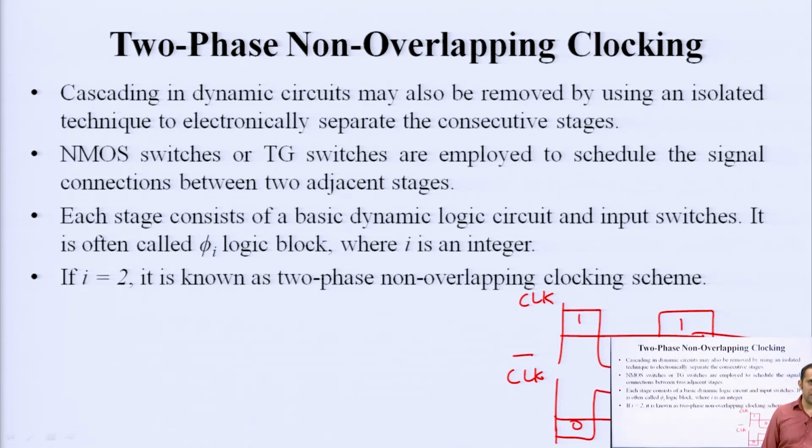In this kind of scenario, if you use a circuit which uses both complementary and non-complementary clock, you would assume or expect one to be 1 and another to be 0. So, if you have a clock signal, pass it through an inverter and get clock complementary signal, right. But every inverter is going to have some kind of a delay. So, at some point of time you might see that both the complementary signals are either 1 or 0, okay, which is not allowed. This is known as clock skew, and in some cases when the output does not follow the changes in clock signal, that is also referred to as clock skew.